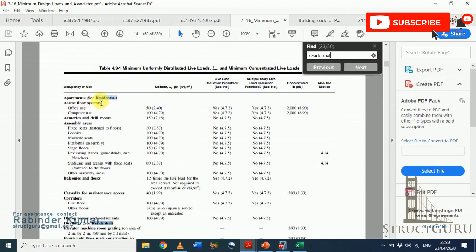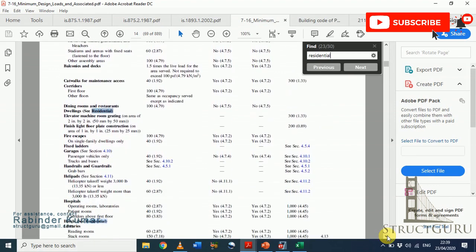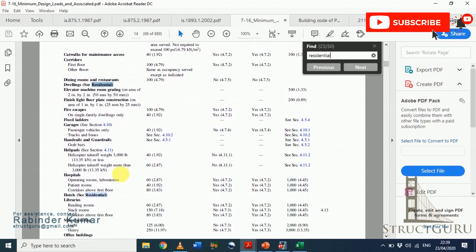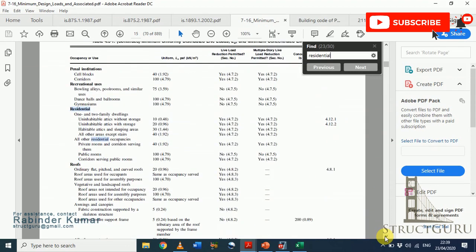C, apartment, C residential. Various occupancy uses are written here. If you are designing office building, you need to refer to this code book in order to see minimum design loads. See, for hospitals the various loads are written, for hotels, libraries. Since we are designing a residential building, we have to look for residential.